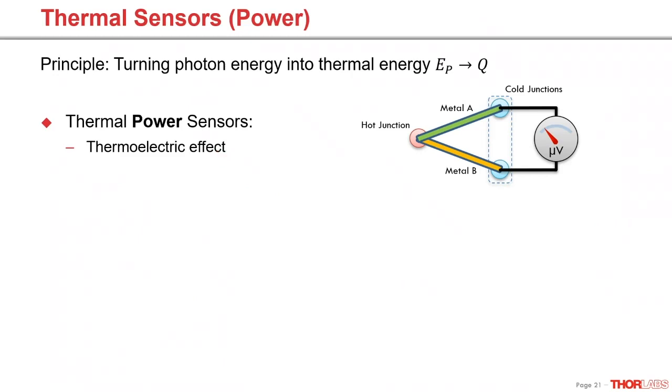Metals or alloys, when heated on one end, release electrons in the direction of the colder side, as long as there is a temperature gradient. This phenomenon, detected by Seebeck, is why the thermoelectrical effect is also called the Seebeck effect, and it varies from metal to metal. Since the effect is not well measurable in one piece of metal, many materials were characterized and ordered in a thermoelectric voltage series in reference to platinum.